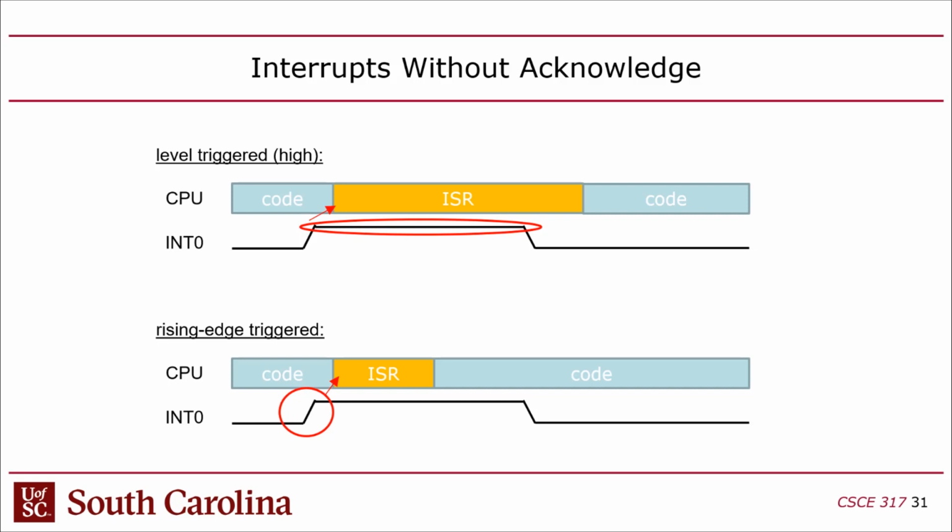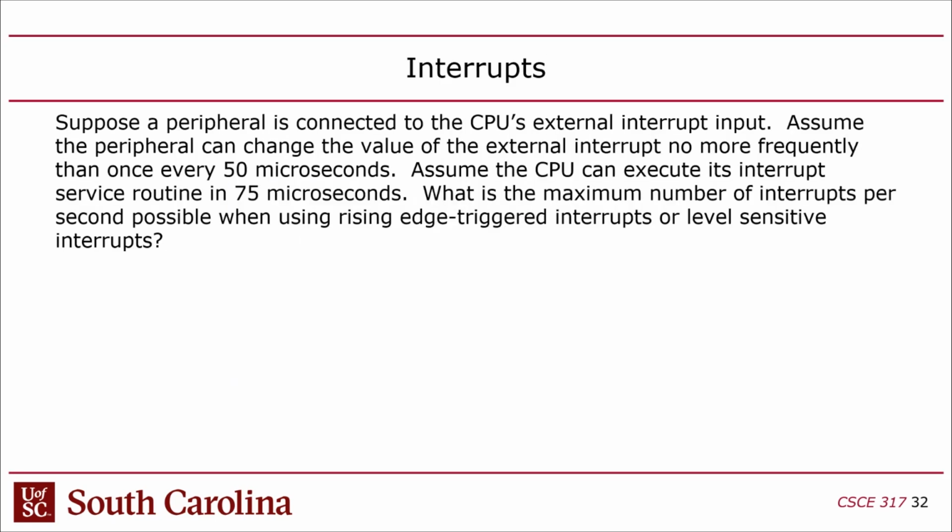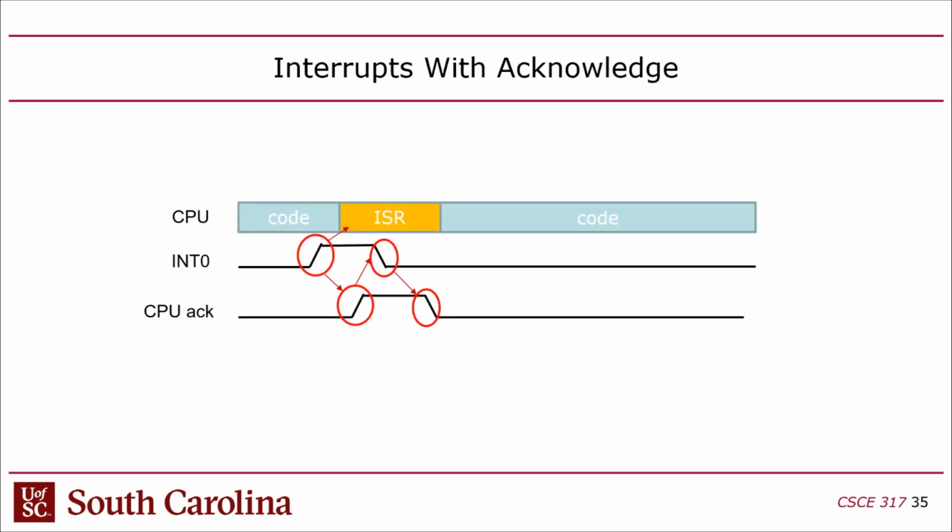So the peripheral doesn't know how long to hold that high, or if the CPU acknowledged it or finished servicing it. For that reason, you should have an acknowledgement, some kind of feedback signal to the peripheral. That's really nice, because the acknowledgement tells the peripheral when the CPU begins acknowledging the interrupt, begins the service. So that allows the peripheral to know when to drop, right?